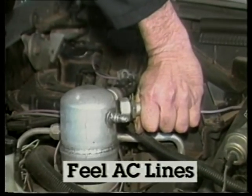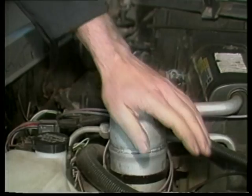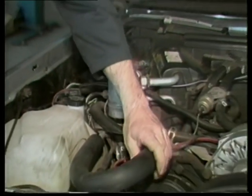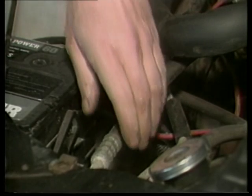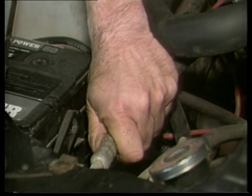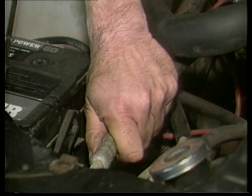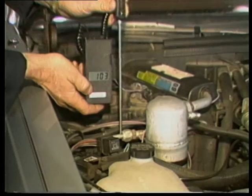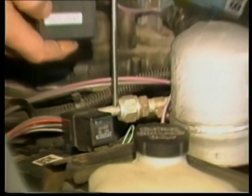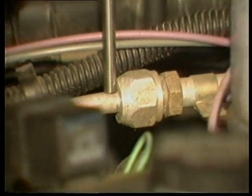Feel the air conditioning lines at the evaporator and accumulator to check general charge and operation of the air conditioning system. Low side lines should feel cool. The high side lines should feel warm. This would tell you that a refrigerant charge is circulating through the system. A digital pyrometer is an even better way to check AC system line temperatures.